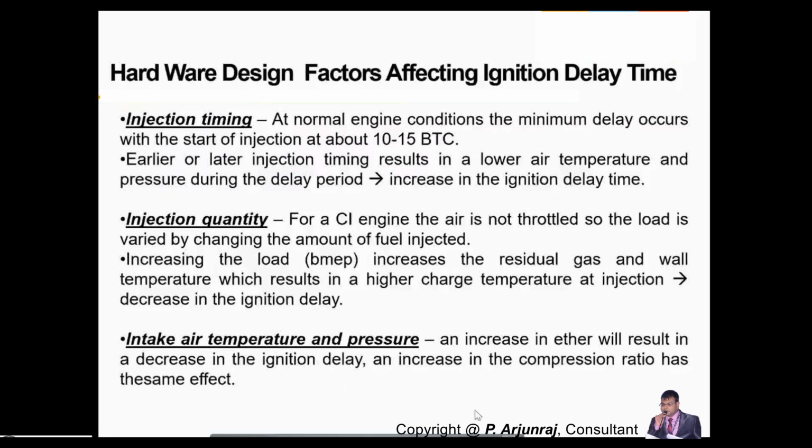Again, the diesel engine already has a high compression ratio. All this will reduce the ignition delay time. When you have less ignition delay time, you have no knocking, or nil knocking, in a diesel engine. But the phenomenon is completely different in a gasoline engine.